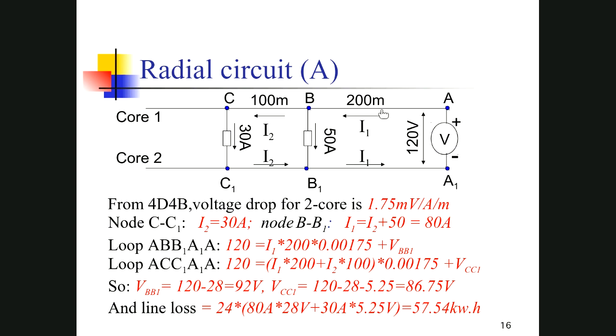So we have this cable, remember. This cable has voltage drops. The cable has a resistance. That is the voltage drop here. The table gives the voltage drop per ampere per meter.